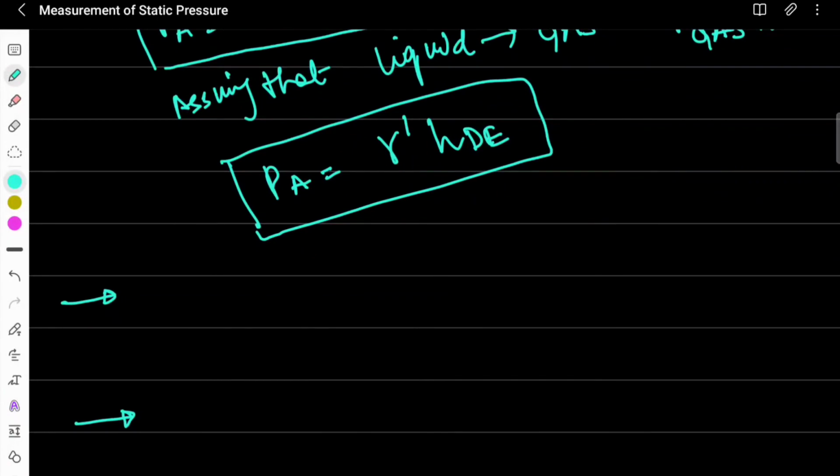So the measurement of the height of rise will be more precise. When the height of rise is much more, the precise measurement definitely helps you figure out the exact pressure, because when the height is higher in the manometer, your pressure head will be more sensitive toward pressure differences also. So the first point is that you should use a low specific gravity liquid, so that the height can be measured more precisely.